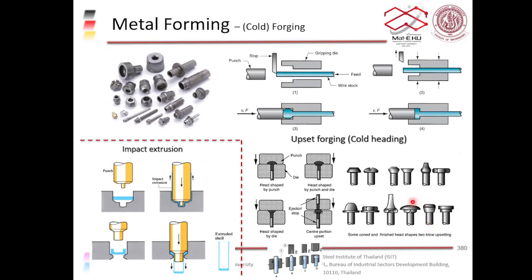So when you have a flathead bolt or flathead screw like this, you do countersinking, right? So the screw will just go and sit in the hole quite tightly. But if you have a bolt that is shaped like this, and you want the bolt to sit flush on the surface, you do counterboring, and the head of the bolt will go into that enlarged hole, right?